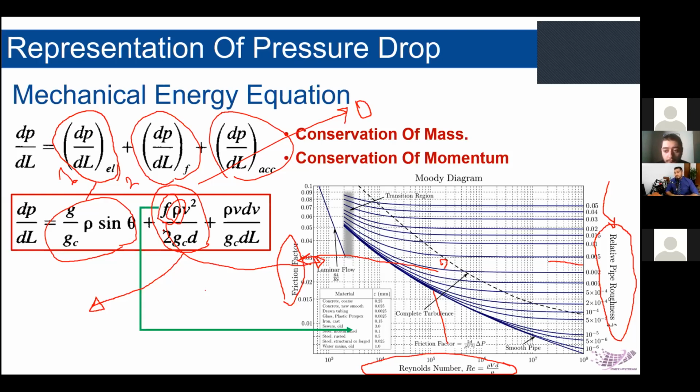If you don't have the well test for that, what you can do actually is have a meter installed on that well, and you can monitor how much flow rate is going inside that well. And then you will remove the meter. You will record the wellhead pressure, and you will record the flow rate. Whenever you record these two things, you will have only one thing left unknown, which is the bottom hole pressure. You will calculate the bottom hole pressure, and then you plug this inside your model, and then you can calculate and predict the future performance with it.